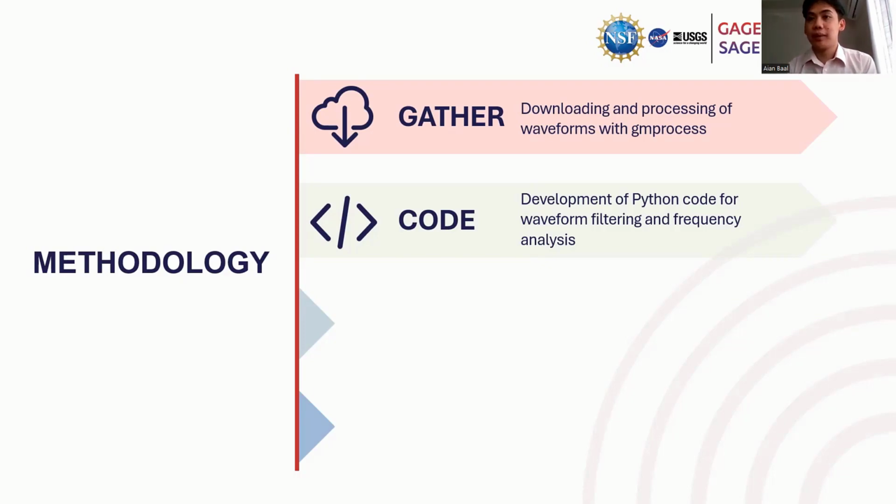which simplifies the approach. We iterated throughout our dataset, applying multiple filters to the data. For instance, we utilized a low-pass filter for frequencies below 1 Hz. Our goal was to identify which frequency range filter would yield a PGA or PGV value equivalent to the unfiltered data. However, this task proved to be challenging, leading us to opt for the filter that provided the closest value to the original PGA or PGV. The selected filter was then designated as the controlling frequency range for these ground motion parameters.